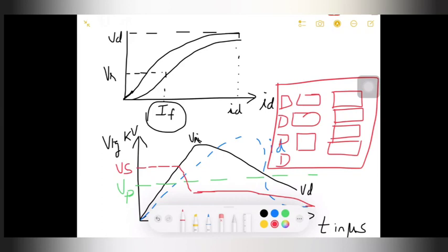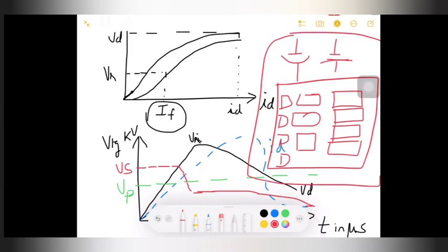They are usually separated by the spark gap. Already we have seen in the previous diagram where we have spark gaps, right? So the individual blocks are separated by a spark gap. The entire assembly is housed in a porcelain watertight housing. Because if any damage is going to happen, I need to protect this entire part, so it is placed within the porcelain housing.